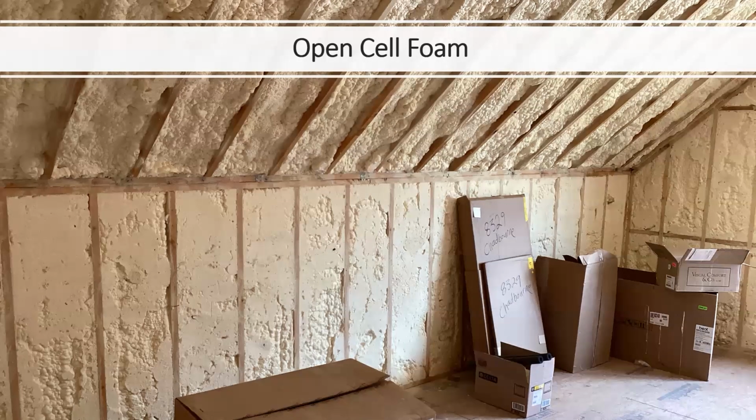Google lists open cell foam as having an R value per inch of 3.5 to 3.6. So if that's true and we do the math, a 2x6 wall is 5.5 inches deep, times 3.6, giving them the advantage of a higher R value, equals 19.8. If the requirement in that climate zone is R19 in vaults, then shouldn't I be seeing most of that cavity fully filled? To me, that's a lot of void, a lot of gap. But if for some reason this is 2x8s, then this installation would be okay.